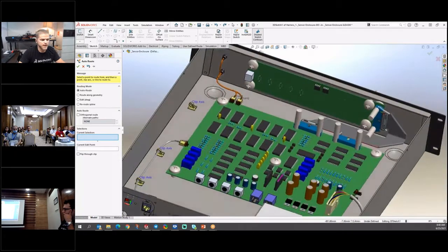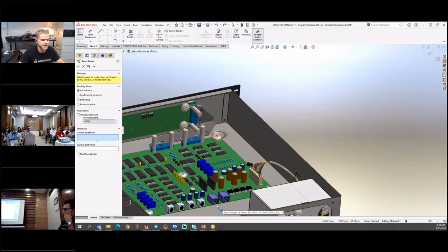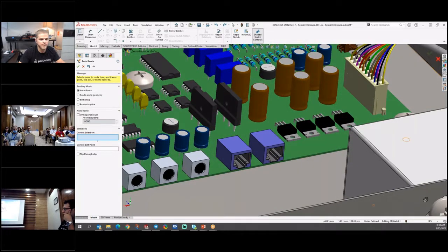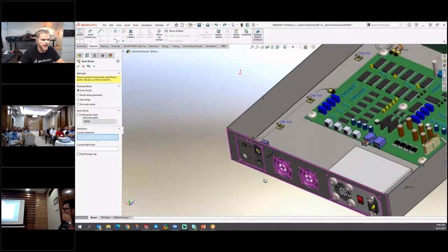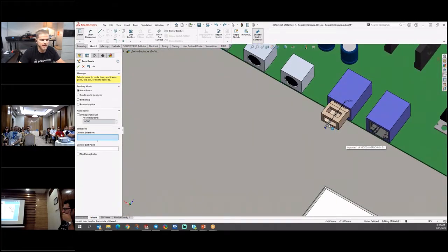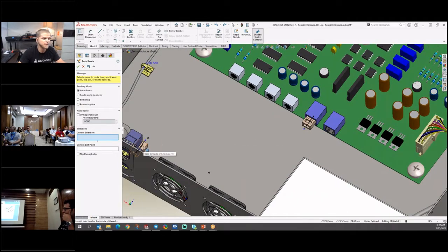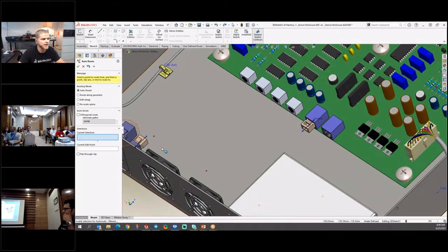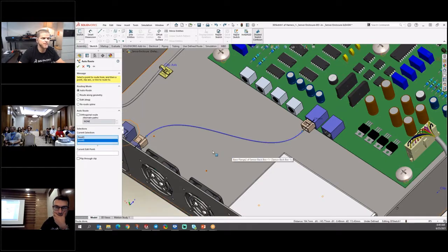The next thing it does is it will allow me to bring in another component. So let's bring in another RJ45 connector. I'll just kind of drop that probably right down here on screen. We'll drop it right here in space. That looks pretty good. And out of each connector, it's applying what's called a stub. There's a little cable stub that's kind of sticking out of each connector there, I should say, not cable. So with each connector, I can auto route from one stub to the other, and routing will handle that little connection for you.